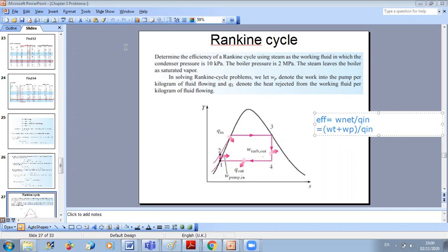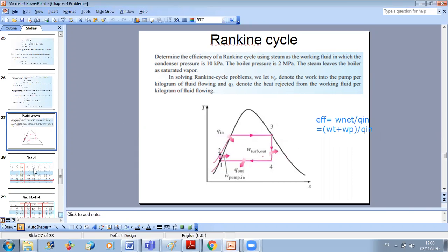So first, as we said, let us determine the characteristics of each point. To start with, we will start with the first point. Now, look, always, when you deal with a circulating fluid, you can use the following formula for a liquid. Keep it in mind. Work in general, I told you last time, when you have a circulating fluid, the work is computed by minus integral VdP.